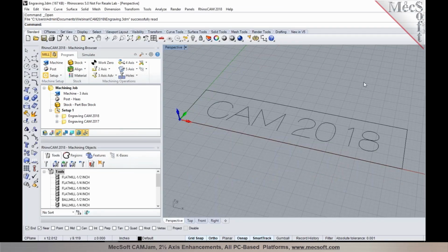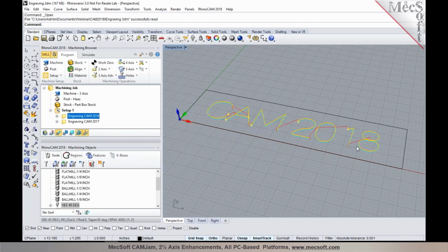So what I have here is basically some curve geometries. This is actually a single line font which you can create in both RhinoCam and Visual CAD/CAM, and in 2018 the order in which the toolpath follows these curves is automatically sorted out. In the previous version, as you can tell, it used to sort the open curves first before processing the closed curves.